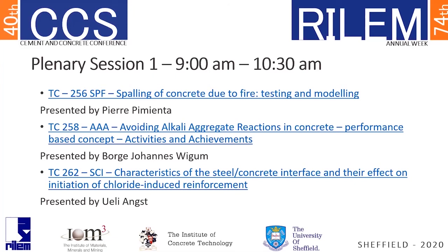They may have different chloride binding behavior. They may have different moisture sorption behavior, and so on. So it's impossible to simplify the cement just down to a matter of pH. All the other effects that are related to the cement play complex roles, so that it is not possible to just say that a pH with more alkalis also increases the resistance against corrosion.